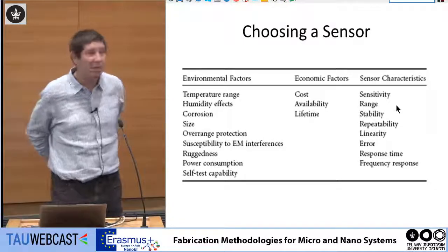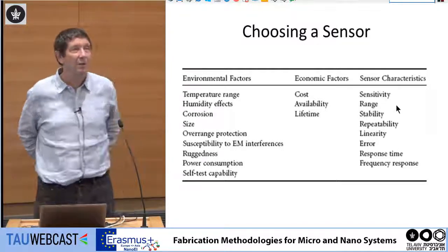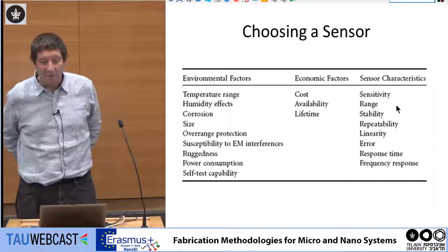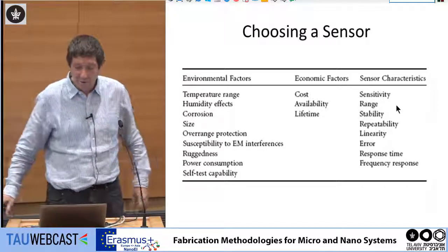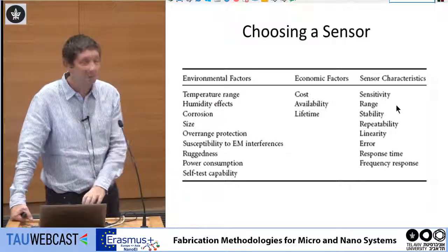Then you have economic factors: cost, availability, and lifetime. And sensor characterization, part of which I discussed before: sensitivity, range, stability, repeatability, linearity, error, response time, and frequency response.